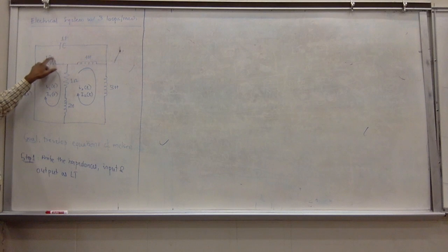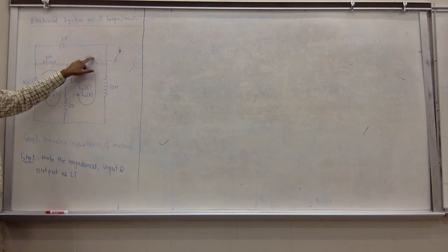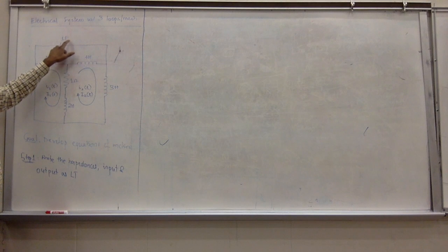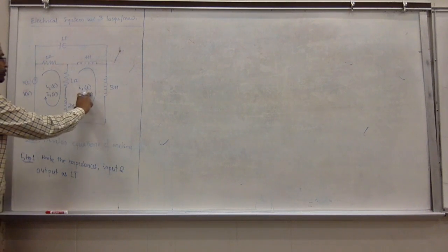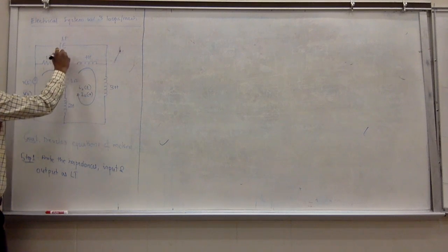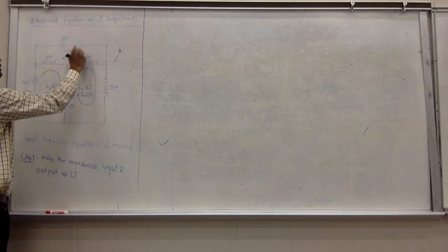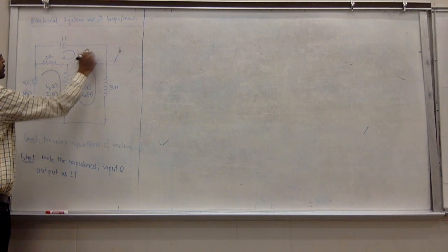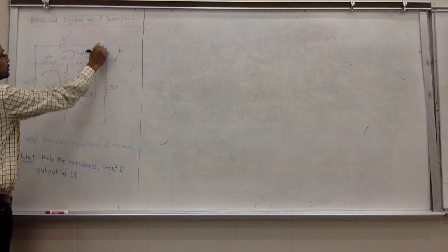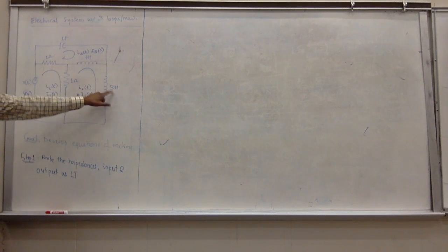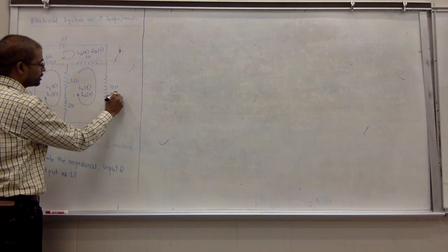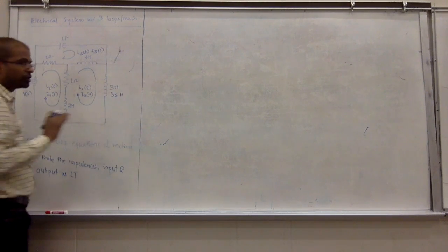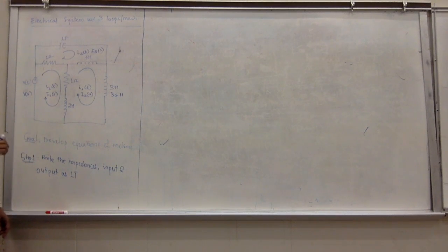So unit of resistance is ohm. Unit of inductance is Henry. Unit of capacitance is Farad. Okay. So it's just the value. If you look at this, this is I2 of S. And if you denote this as I3 of t, the Laplace equivalent would be I3 of S. What would the Laplace equivalent of this be? Inductance would be 3s. You can still maintain the H. H is only a unit, nothing else.